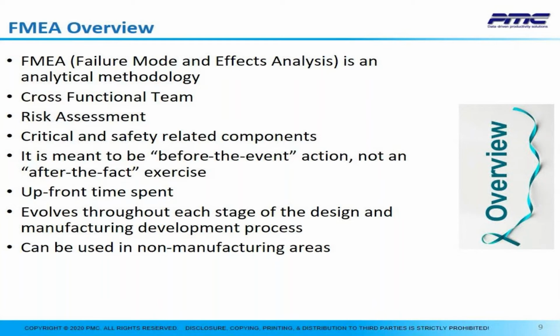It is meant to be a before-the-event action, not an after-the-fact exercise. Upfront time spent properly completing an FMEA will minimize late change crises. It evolves throughout each stage of the design and manufacturing development process and may also be used in problem solving. And finally, it can be used in non-manufacturing areas, such as analyzing risk with a safety system.